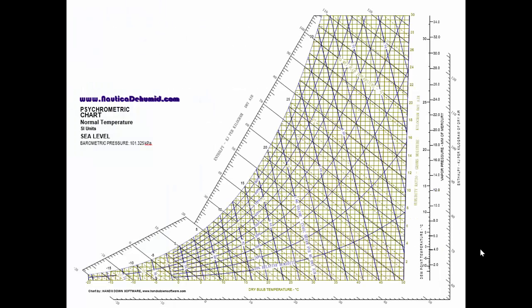The dew point temperature can be located on the psychrometric chart using this vertical scale, as you can see on this particular psychrometric chart. So if we know the thermodynamic state, let's assume that we are located at this point, we can move horizontally following the constant humidity ratio lines and locate the dew point temperature of the state using the left-hand side of this vertical scale, again on this particular psychrometric chart.